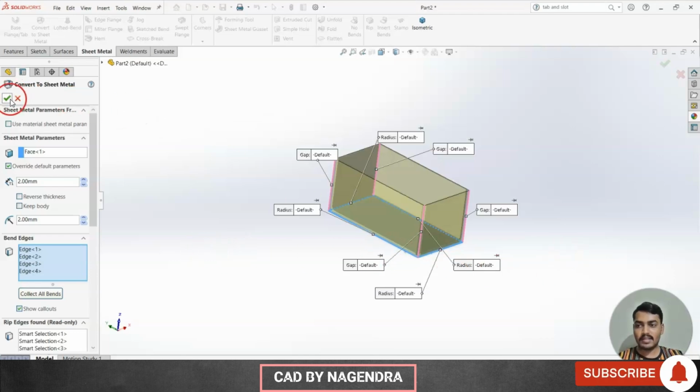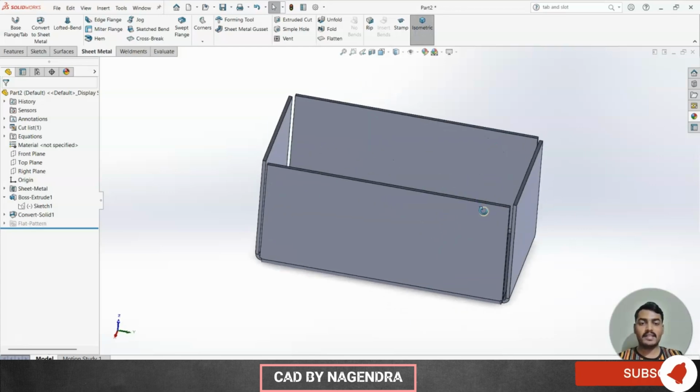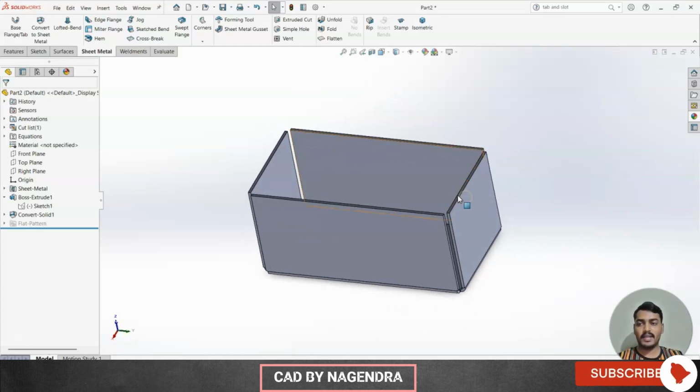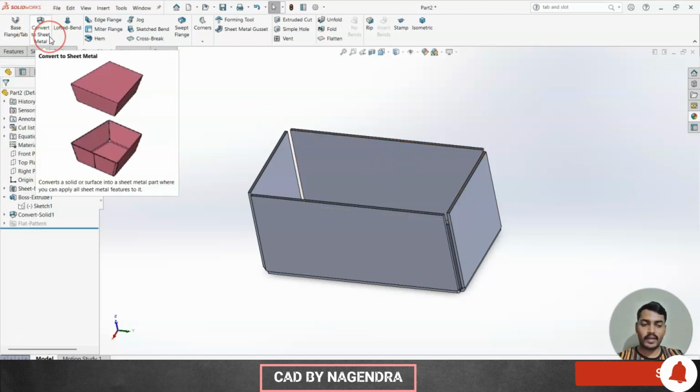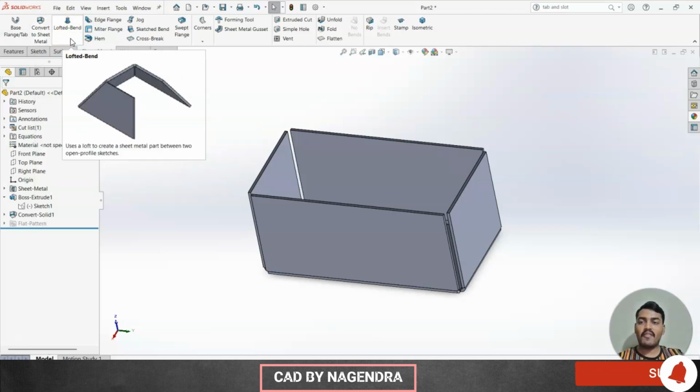Then just I'll say okay. Now you can see part design is converted into sheet metal design. Like this, we can use this option called convert to sheet metal. We can convert part design to sheet metal design. Then next we are having here lofted bend.